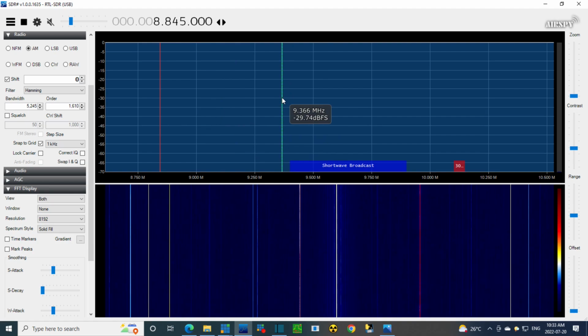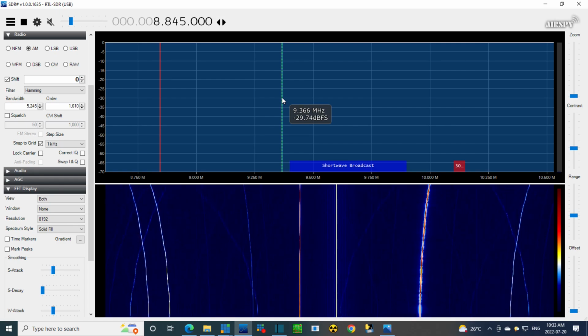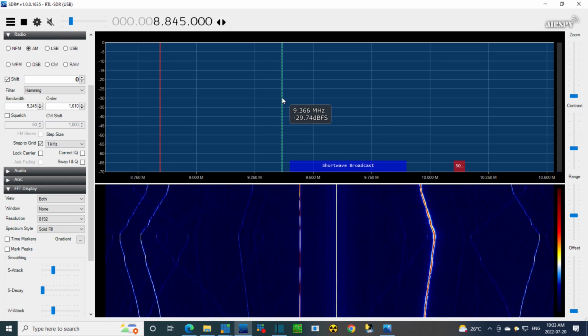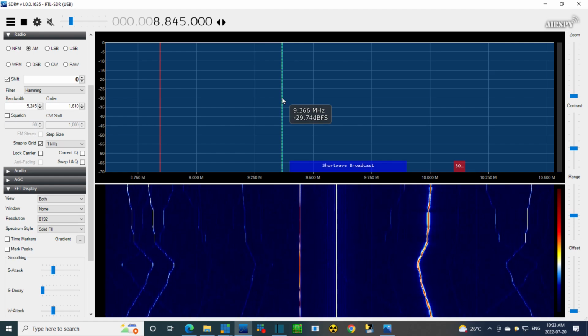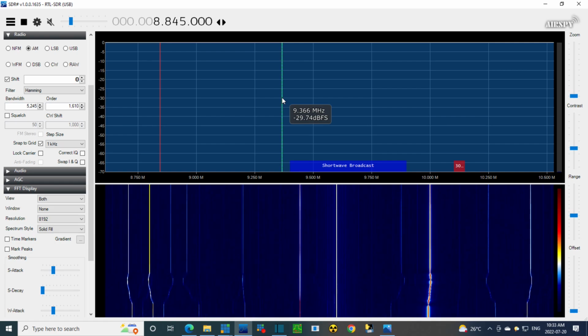I'm going to tune the radio a bit. I'm going to tune it up, so the oscillator should go up. A lot of things going down in frequency. Isn't that weird? All that weird stuff in there. The only conclusion I can come to is that thing up around 10 is the actual local oscillator. The local oscillator is running above the target frequency. That's how they've set this up. And it's out.